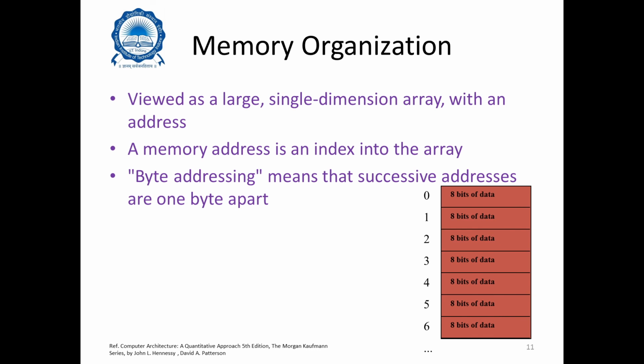Now if I ask you what will be the instruction format for ADDI? ADDI will have instruction format as I type, similar to LW and SW. Although it is doing an arithmetic computation, it is working on an immediate field. So for that immediate field, we need a 16-bit constant value. So if ADDI is $S1, $S2, 100, then we know that we need to add the content of S2 with 100, which is the constant value, and store it back into $S1, right? So therefore the value 100 has to be stored in that 16-bit field, which you actually add with S2 and then store back to S1. So that's how it basically works, and you will have the value of opcode also specified there. The opcode value will be 8 in this case.